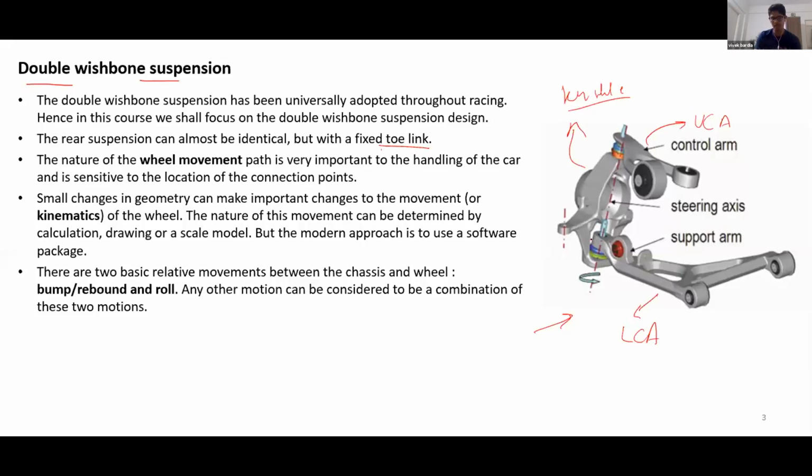That is to say that these points, which are called hard points, points of attachment, like this point, can be varied significantly without affecting kinematics or compliance of the suspension. So what you can also do is that I have seen some teams also use a McPherson strut both in the front and the rear.